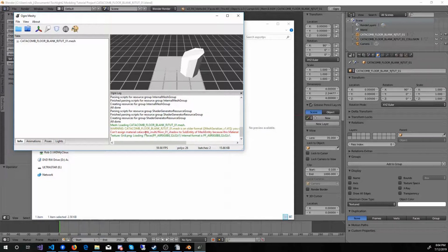So we would have to create the material file it's looking for by hand. A good way of doing that, since we edited an existing asset, is just to copy that material file here and rename it, especially since we're using the same texture. And if we want to see the texture applied, we'll also need the texture image in this folder.